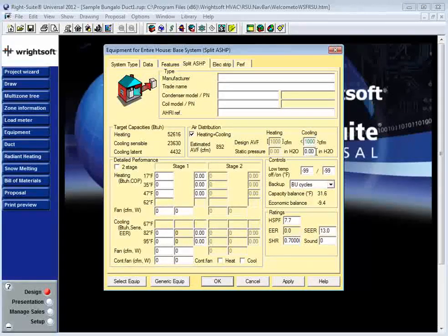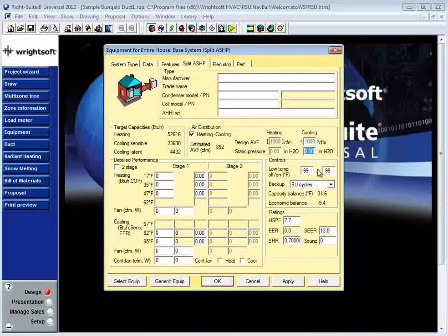At the end of the day, it's these two numbers, the CFM you'll be moving through your system and the static pressure conditions under which your fan can deliver that CFM, that makes the equipment selection screen the first step of the duct design process.